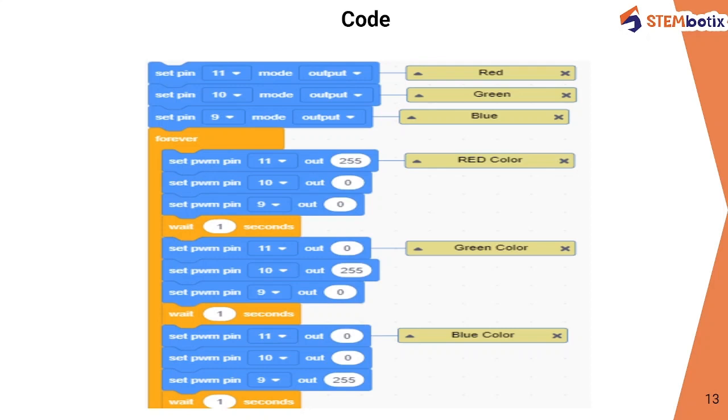So potentiometers are basically used to control the flow of the voltage, and we can indirectly control the brightness of the LED. The technique used to control the brightness of the LED is called pulse width modulation, or simply PWM. If we don't want to use the potentiometer, it's not possible every time to connect an individual potentiometer to an individual pin, right? So here we can connect the pins where we need a PWM signal, or where we need to control the brightness, to our PWM pins.